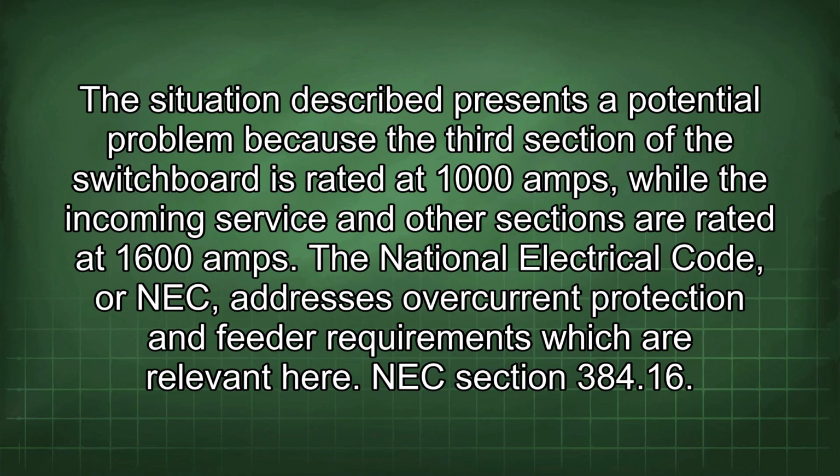The situation described presents a potential problem because the third section of the switchboard is rated at 1000 amps, while the incoming service and other sections are rated at 1600 amps. The National Electrical Code, or NEC, addresses overcurrent protection and feeder requirements which are relevant here.